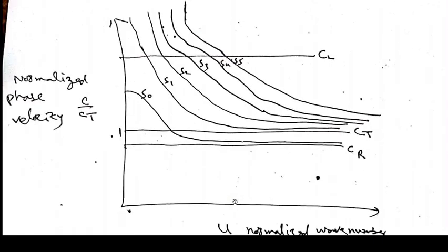Now this is the spectrum which I have already shown you in your previous lecture, figures 2.1 and 2.2, using the dispersion relation for an isotropic plate, where we have written which type of material we are using, and given the material constants and the values of CL and CT.